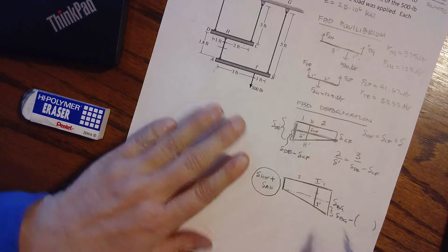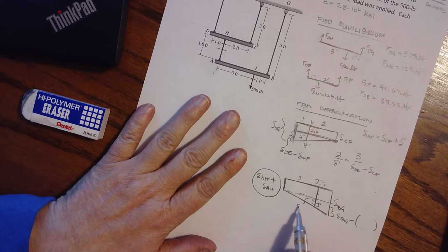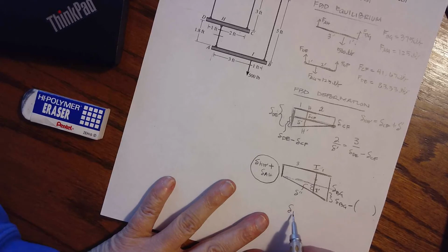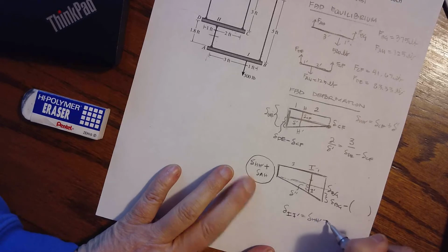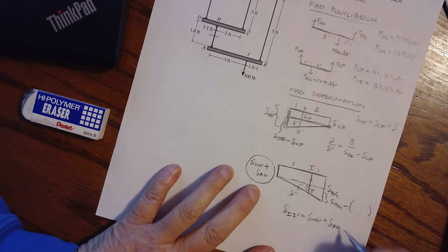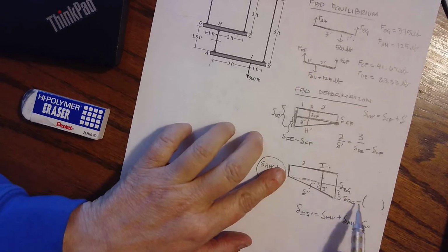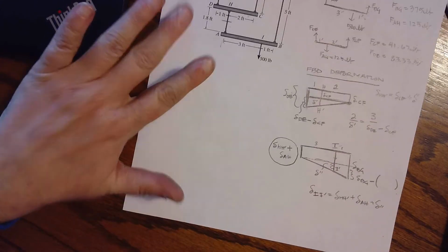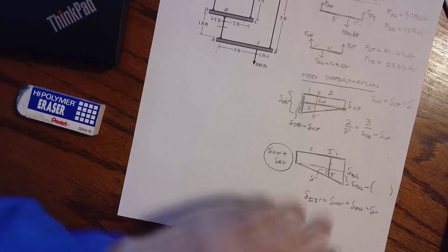Okay, and then we can use similar triangles to find delta prime prime. And I know ultimately that the displacement from I to I prime is delta H to H prime plus the elongation of that cable plus delta prime prime, which is the little extra bit that we come down over here. So that sounds really confusing, and it took me a long time to explain, but if you can draw this out, deltas are easy.